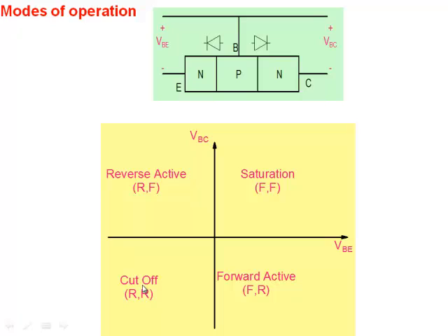Very low current here. So I'm going to have current flowing in my transistor in all 3 of the other regions. Significant current will flow here, here, here. The only place where very low current flows is in the cutoff. Okay, so these are the 4 modes in which the transistor works.